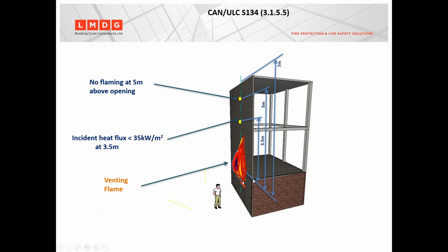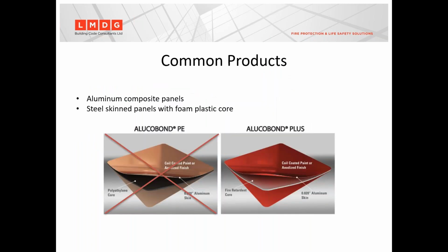So during this 1-hour test, the fire is started, and the fire gets so large that the immediate surroundings above the window, if they're not non-combustible materials like concrete and steel, they'll just get turned to ash. But that's okay, that's expected in the test. And then the test proceeds, and then this little example here, this final slide would indicate a failure because it's illustrating flames climbing above that limit. So this would have been caused by the fire from the chamber catching the combustible cladding on fire and the fire spreading too much. It would not meet the requirements of the test.